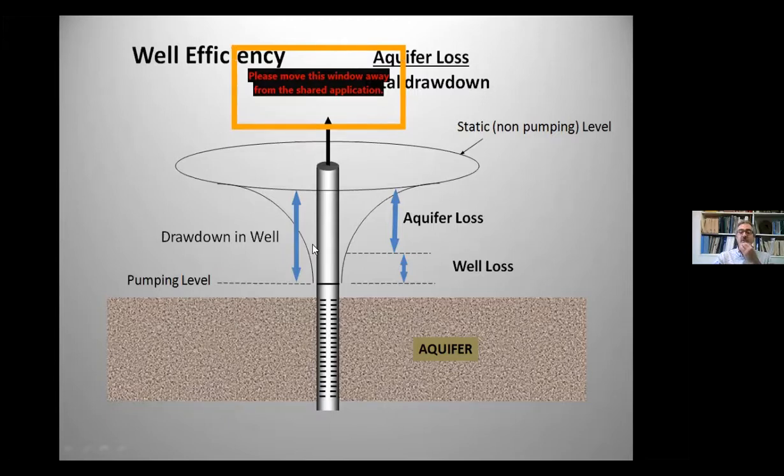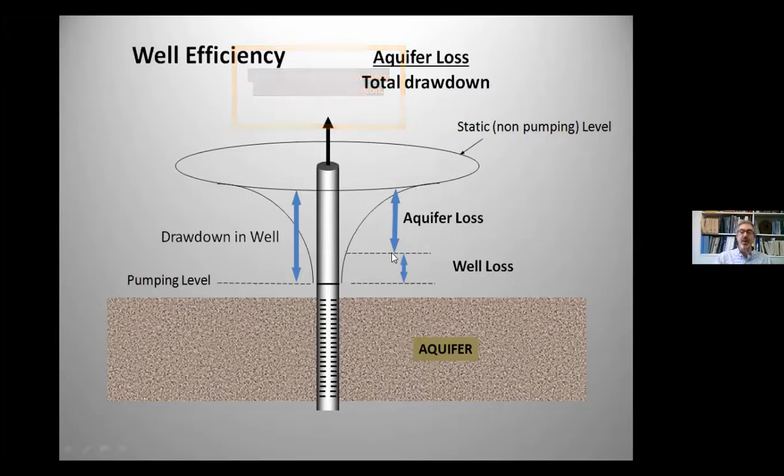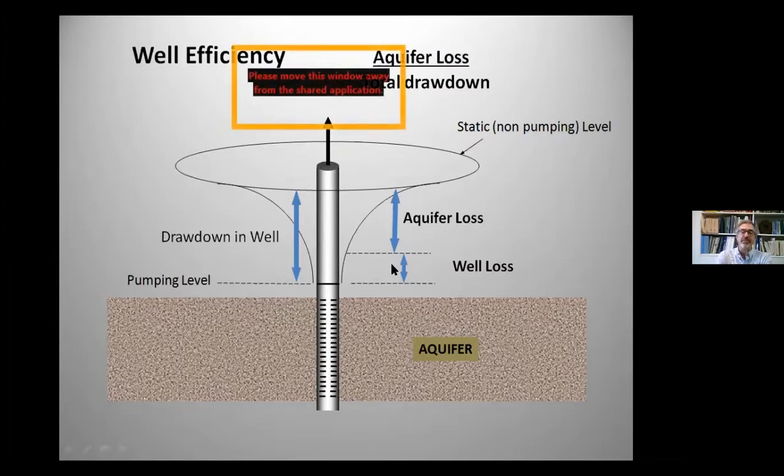And these we can't control. This is what Mother Nature says. You stress the aquifer, as we understand, and this is the amount of loss that you will receive. These additional well losses, these several meters of additional well loss, for example, will be added to the total drawdown of the well because of things like improper development of the well or improper gravel pack size.